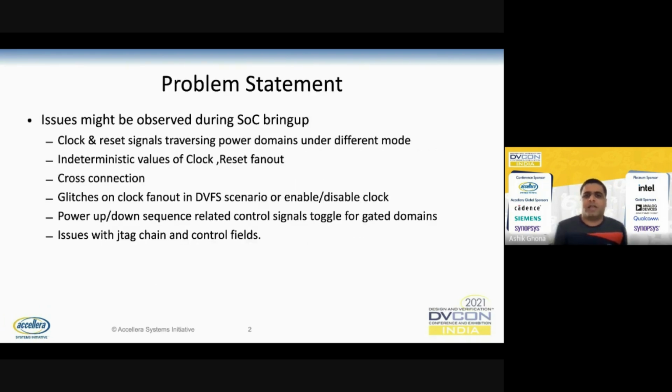Today's ML and Vision IP based SoCs have numerous IPs integrated into them, with a complex power up, power down sequence, and clock and resets traversing from source to destination under various different modes. We might see multiple issues while doing the SoC bring up on board.